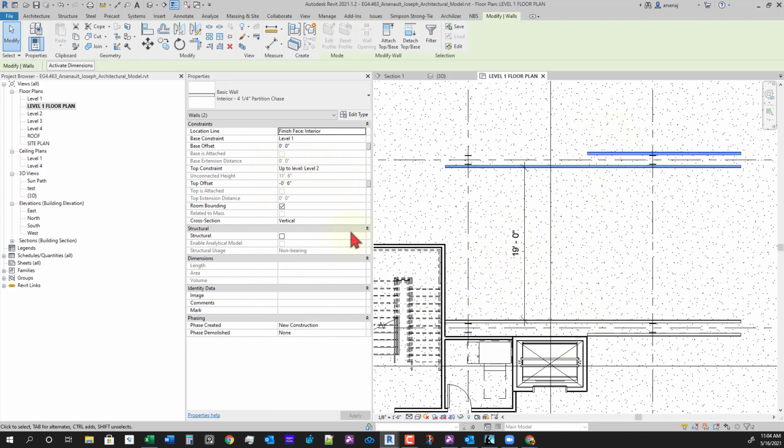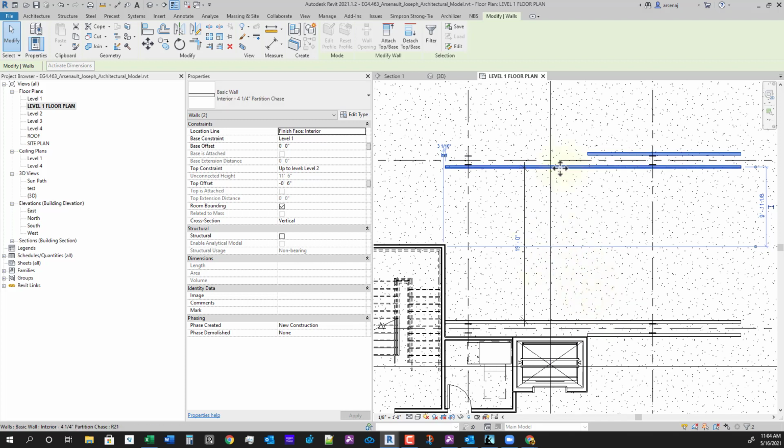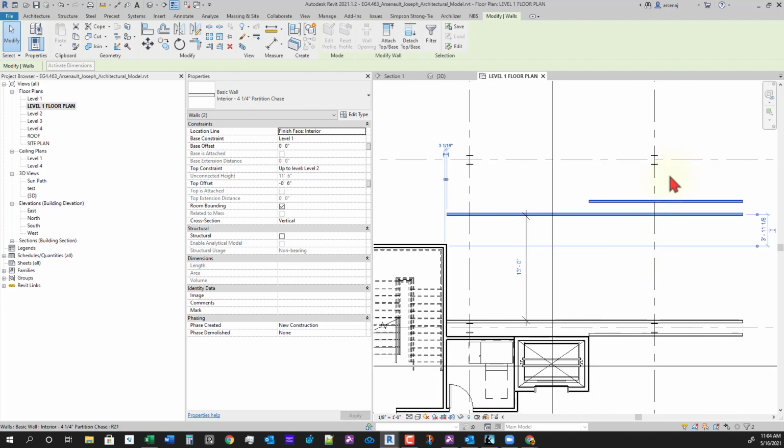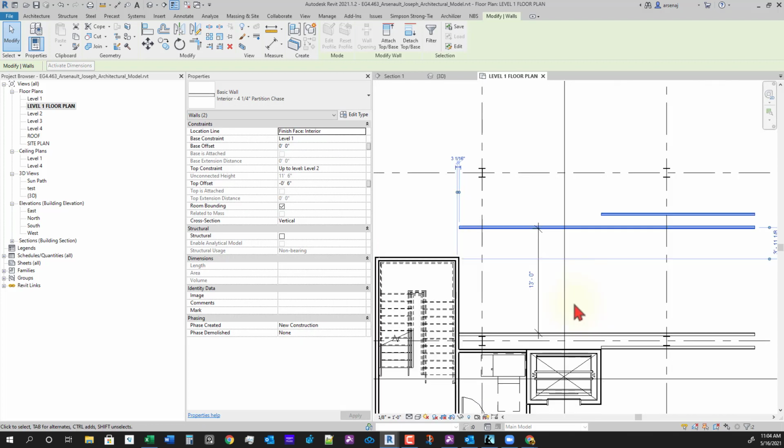So I'm going to select both these walls. Then up at the top left, I'm going to activate dimension, and I'm going to, what did we say, 19 feet? Oh, I only need 12 feet. Let's see. That's fine, actually. We'll still select both these walls. We're going to change this overall height to 13 feet. And we'll just add column furring around these walls here.